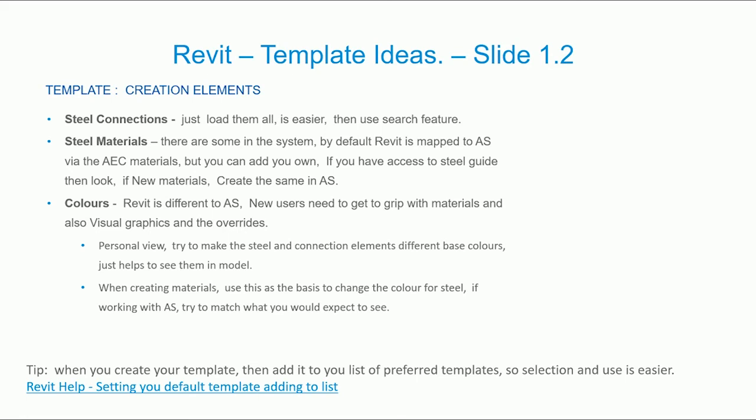One note about levels that I meant to mention was that sometimes I found it's better, if you're importing from Advanced Steel, just to have the level 1 at the bottom if you've got levels inside the Advanced Steel model, or else you end up having offsets from the level. So sometimes it's just better to have the level 0, and work about the 0 option.